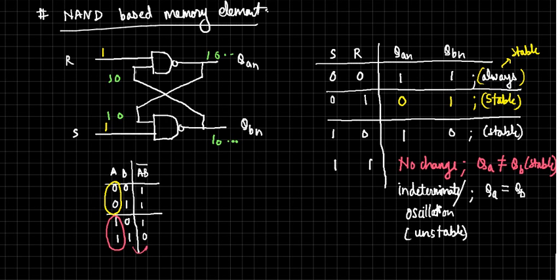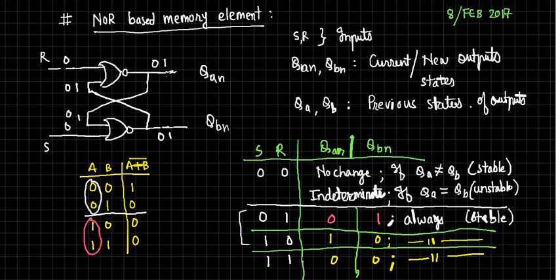Why? Our aim was, what was our purpose? Our purpose was to create a memory cell. It should retain a bit of information. Is that purpose served? Here, in the previous case also, assume that usually the S is the input. Whatever the S is, that is getting retained at the Q terminal, always, and that is a stable situation. Forget about these situations.